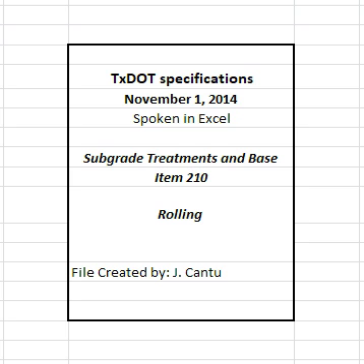2.4.1 Light pneumatic tire. Furnish a unit with at least 9 pneumatic tires, with an effective rolling width of approximately 5 feet. Capable of providing a total uniform load of 4.5 to 9 tons, and with tires capable of maintaining a minimum ground contact pressure of 45 psi. 2.4.2 Medium pneumatic tire.